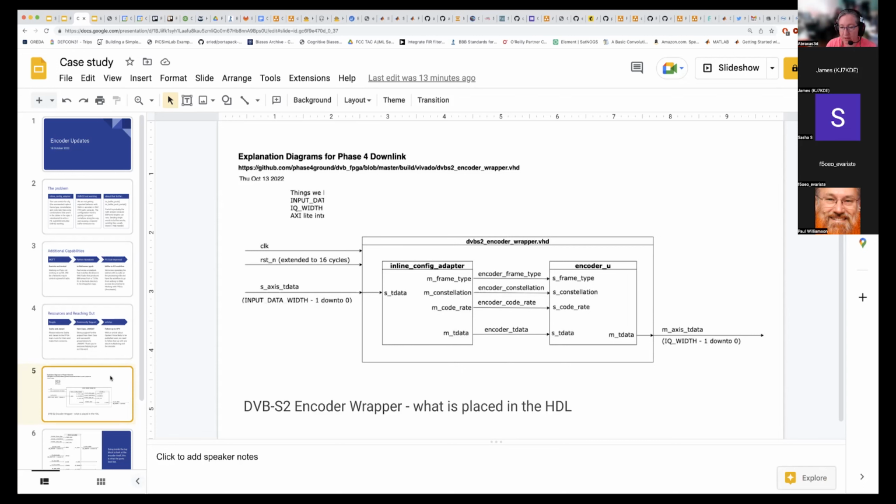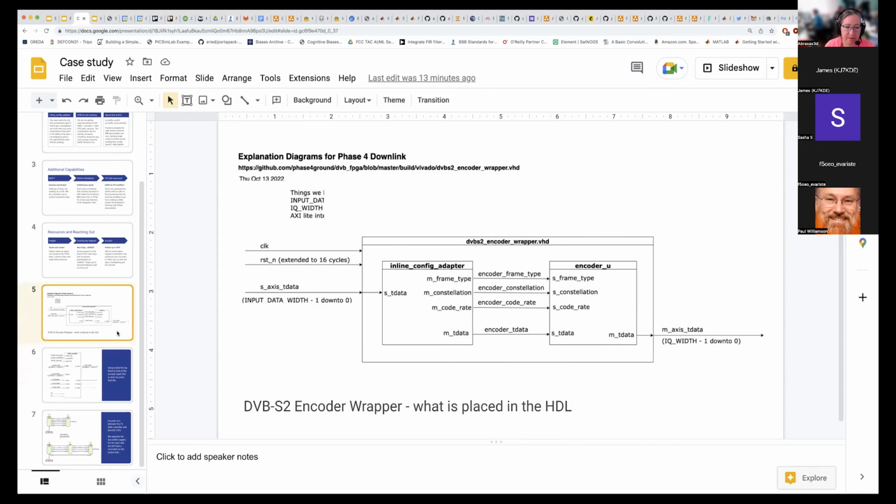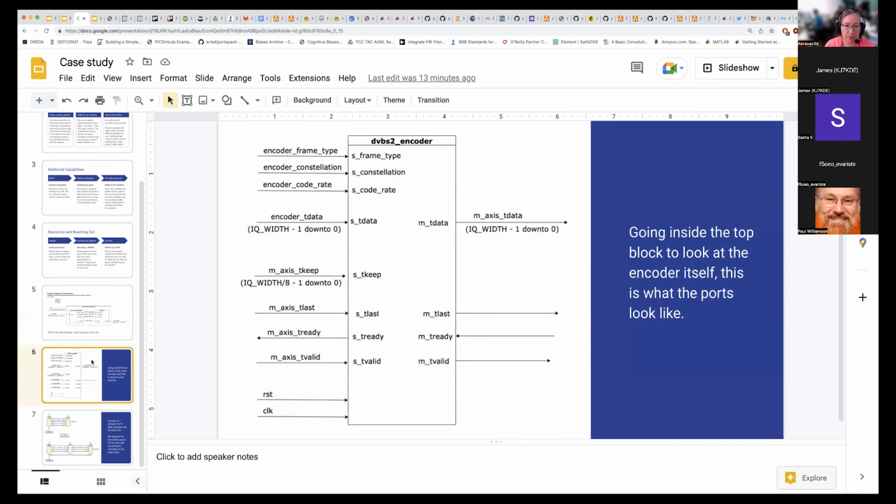And then what comes out is IQ data. So it's 16 bits I, 16 bits Q. This is the format that the DAC FIFO is expecting. However, we're outputting 32 bits at a time, not 128 bits wide. That's the next thing I think we should probably fix, and we'll probably start seeing better spectrum results on the ZC706.